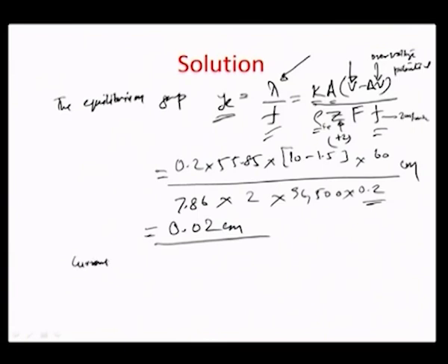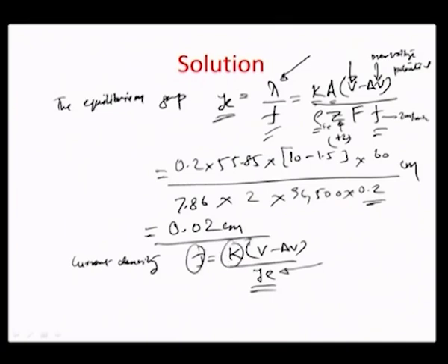So the current density, as we know, J is represented by the conductivity of the electrolyte times the voltage minus overvoltage potential, which is available per unit equilibrium gap. We assume that the Y value here remains at equilibrium, the Y is kind of constant. Okay. So the current density is actually conductivity times the field.